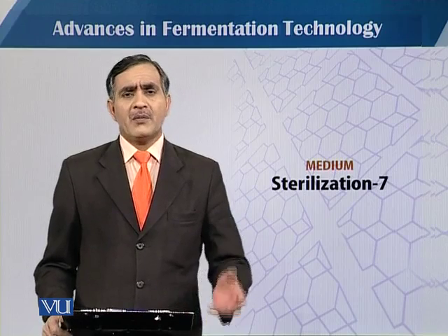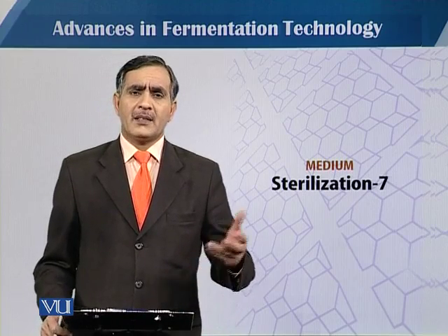What is in situ sterilization? In situ sterilization of the fermenter is done in the same place where the fermenter is. So we just supply the steam to the fermenter to sterilize it, and that is known as in situ sterilization. The ex situ sterilization is only for small scale or shake flask level, because we keep our material or fermenter vessel in the autoclave and then we sterilize. This is known as ex situ sterilization.